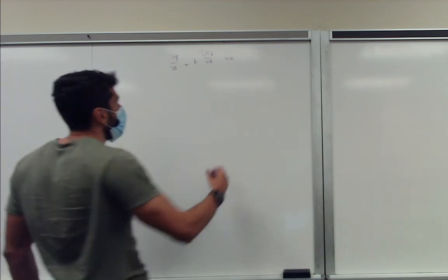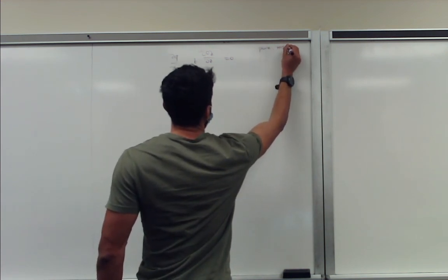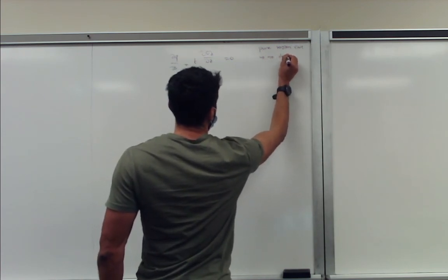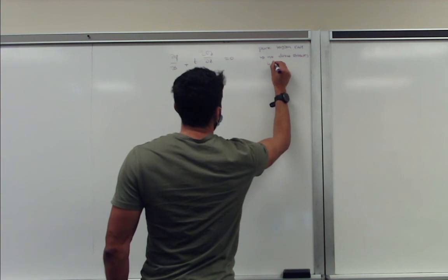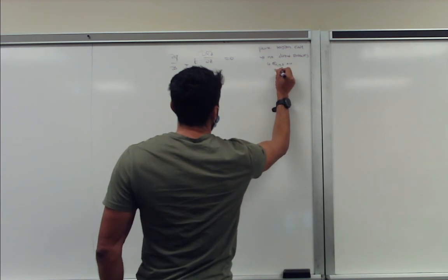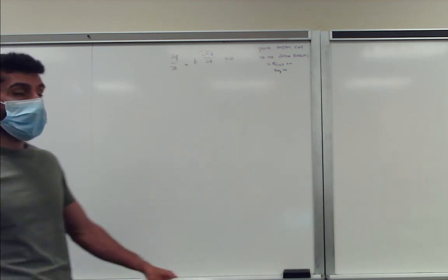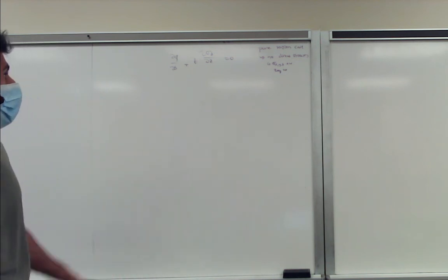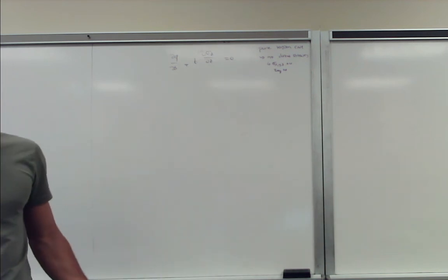And if you remember correctly, for torsion, we said we have a pure torsion case. There are no direct stresses, so sigma x, y, z is equal to 0, and tau xy is also equal to 0. If we have no sigma z, the variation of sigma z with respect to z is equal to 0.